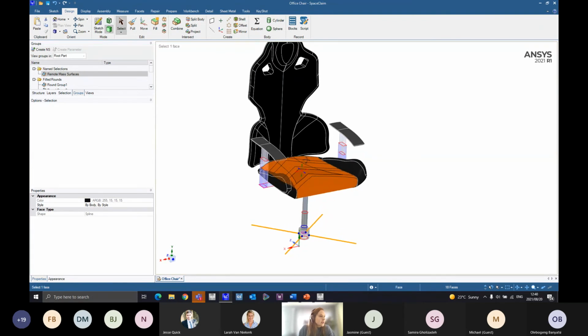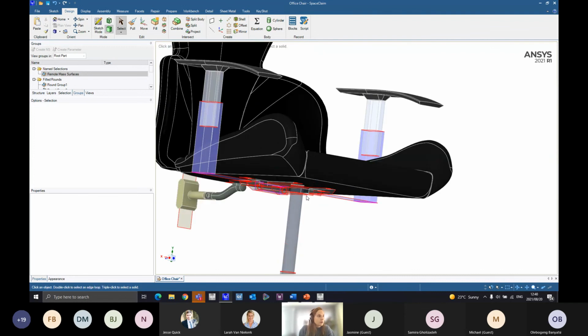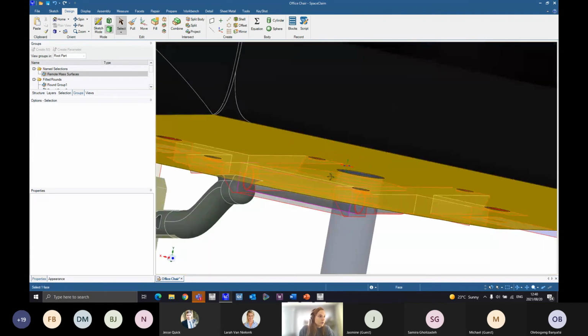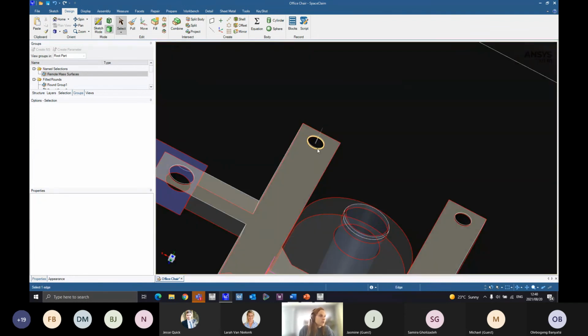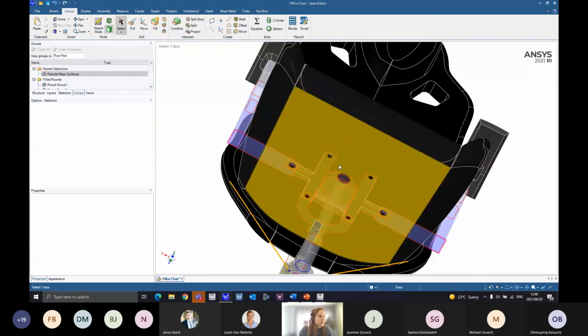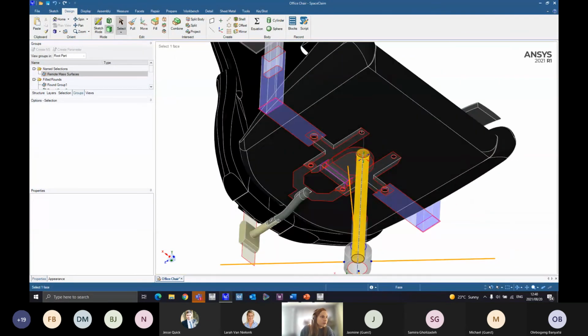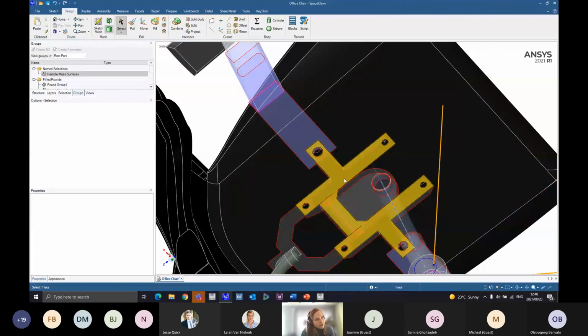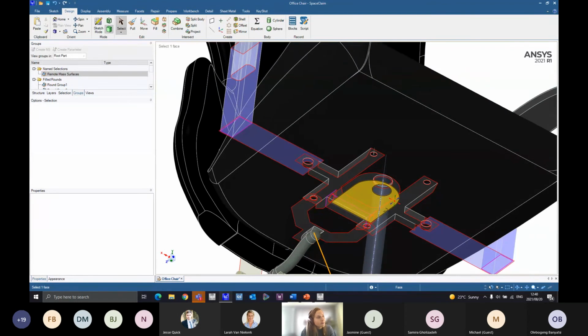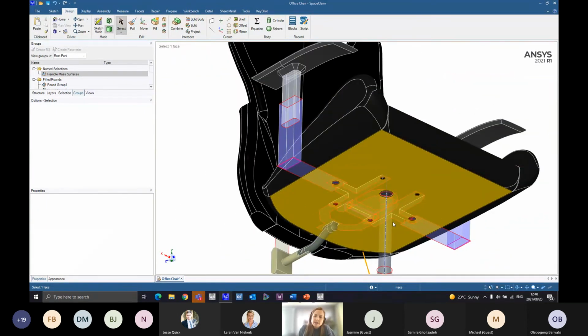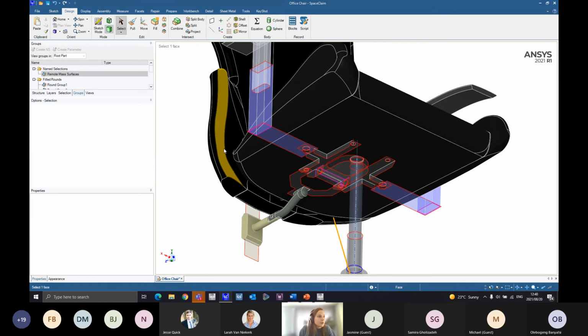So another thing that is very useful to create named selections for is your edges or maybe your washer faces where you have bolts. So as you can see, this geometry did not include bolts over here or screws or whatever they used to connect this, but I was going to represent it as beam elements or joints in any case. So in that case, when you are in mechanical, and we'll cover this next week, you use something called the object generator, and this just automates something repetitive.